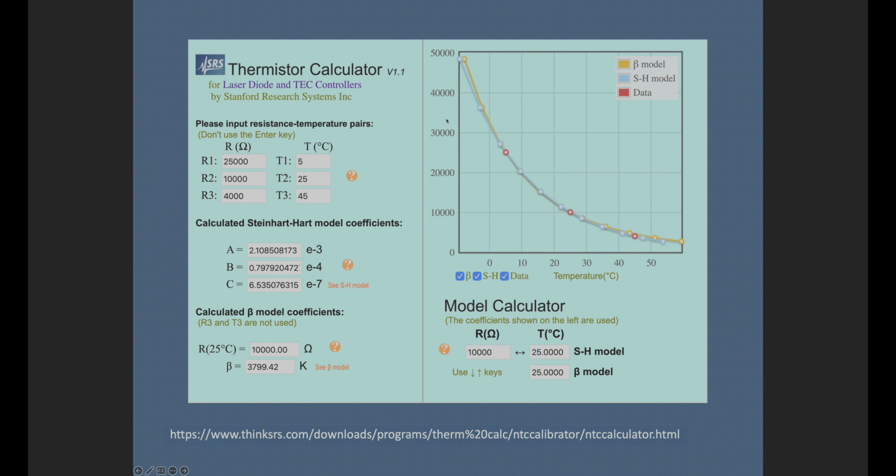Let's look at the 10K at 122, which is about as much as that epoxied can take. It's usually around 120 to 125 C for the epoxy-covered. 420 ohms at 123 C. We'll continue to take readings, and we'll start back down again toward room temperature.